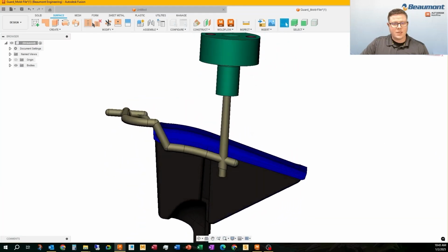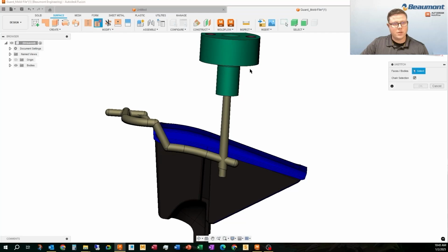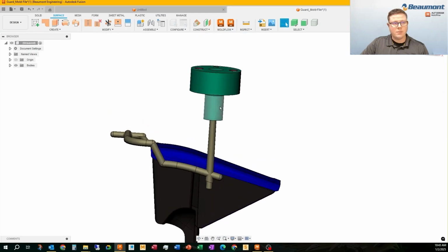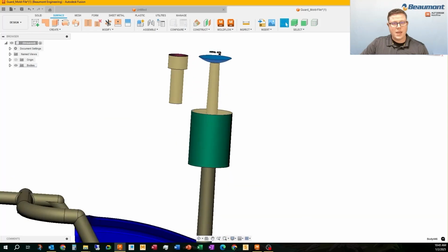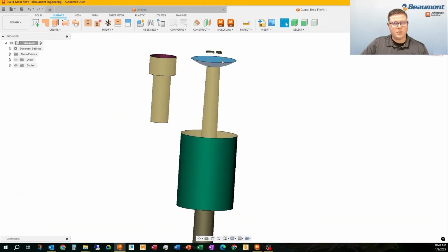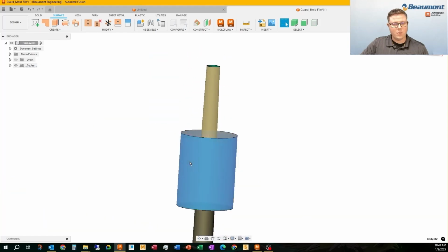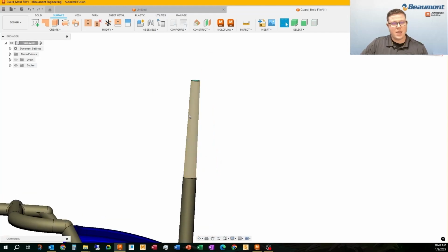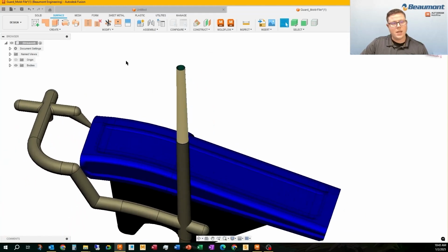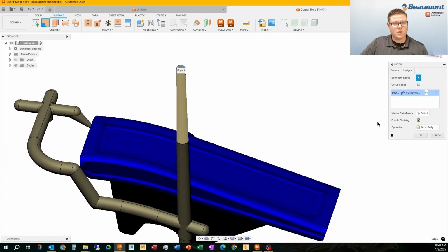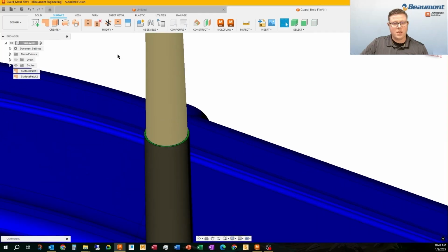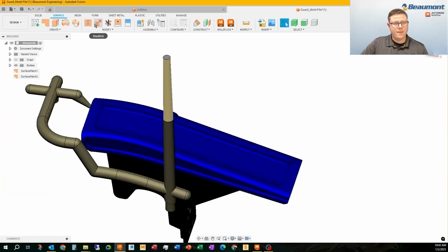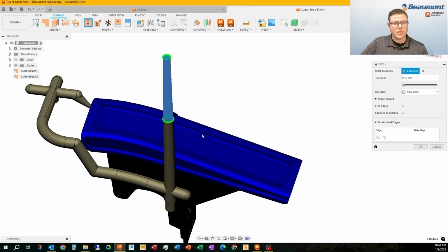And in this case, for my sprue geometry, I just have the bushing. So I'm going to go into the surfaces and unstitch this sprue bushing. What I'm doing is deleting and simplifying these surfaces. What this allows me to do is then cap the ends of the sprue bushing and easily stitch them and convert them to a solid body. So you see me capping the ends here. I'm then going to stitch.